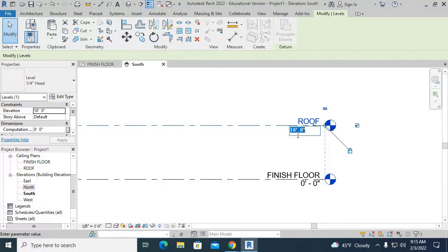I like to play it safe, okay? Not that I'm gonna have a house that's like 20 feet high, but I usually put this at around 25, 30 feet high so I can be sure that I'm at the very top looking down, right? So let's make this 25 feet.